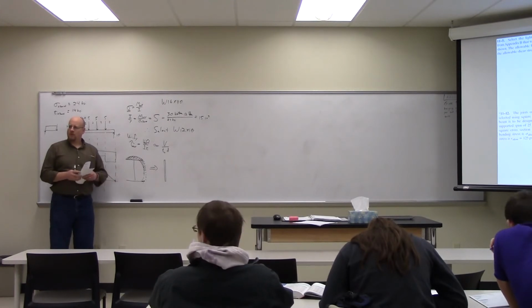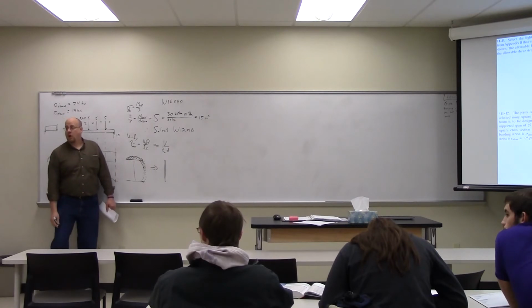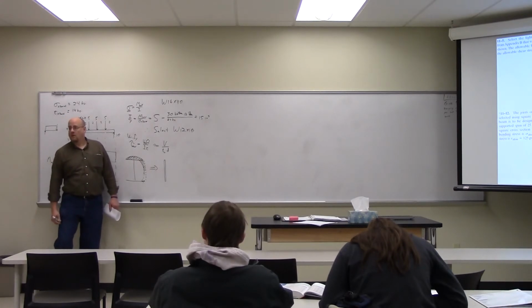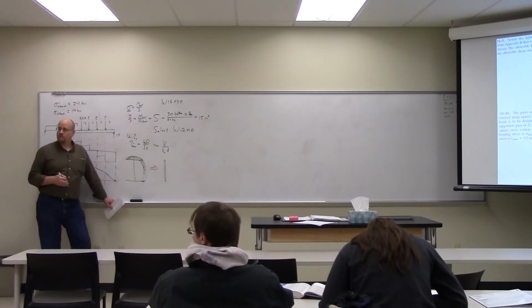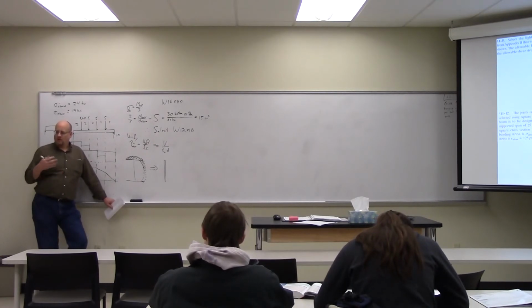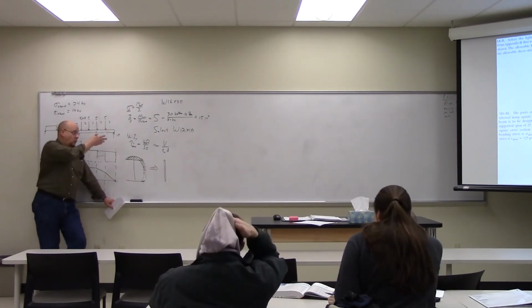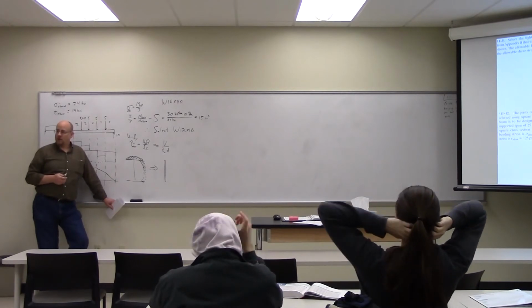So we've done that on our test. We didn't talk about that, unless I specifically tell you. So it depends on the code. It's all driven by building code and that kind of thing. There's some regulating body that says for this application you can use the approximate stress, or no, you have to go back and actually calculate the peak shear stress.